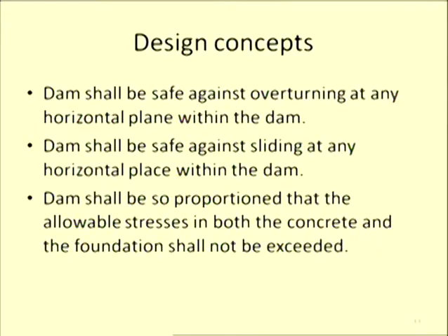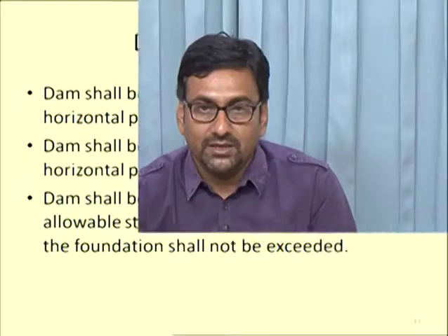And third, the dam shall be so proportioned that the allowable stresses in both the concrete and the foundation shall not be exceeded. Anywhere in the concrete or in the sound rock, the stresses generated should not exceed the permissible limit. Otherwise, there would be crushing of the toe, or crushing of the heel, or the foundation will get crushed. That situation should not occur.